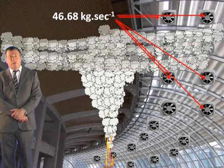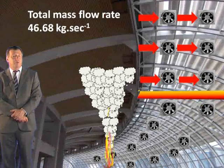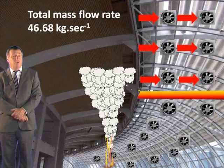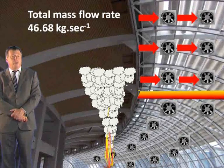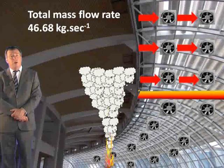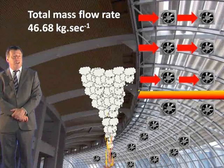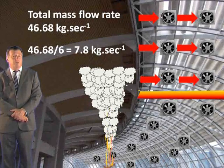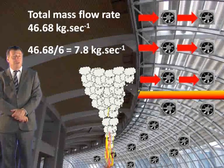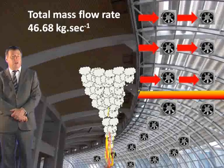In our example, the total flow rate for all smoke is 46.7 kilograms per second. And remember that this smoke is flowing out of all 6 of the ventilators that are provided in the reservoir. So we also know that the most smoke that will flow out of any one ventilator is 46.7 divided by 6, which equals 7.8 kilograms per second. This actual amount that is flowing out of each ventilator is much lower than the M crit limit, and so we can be confident that plug holing will not occur in this case.